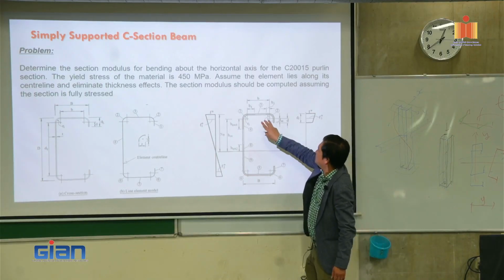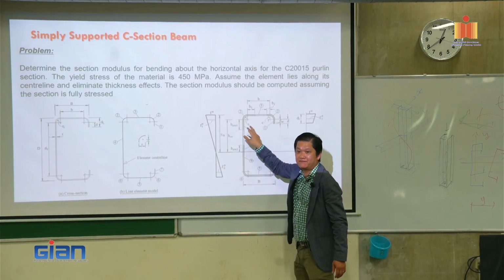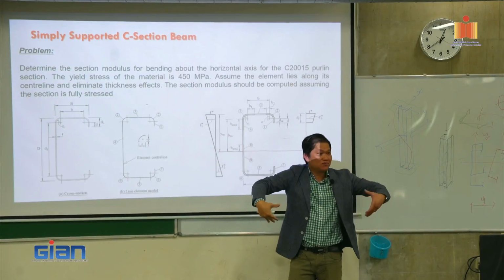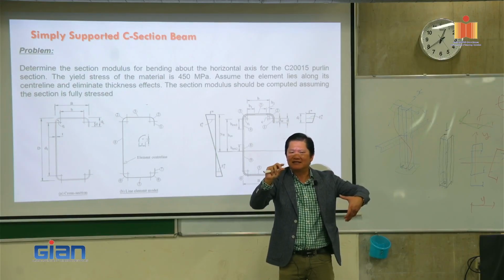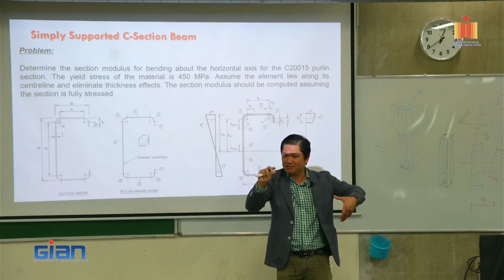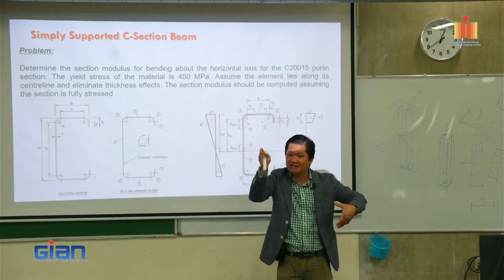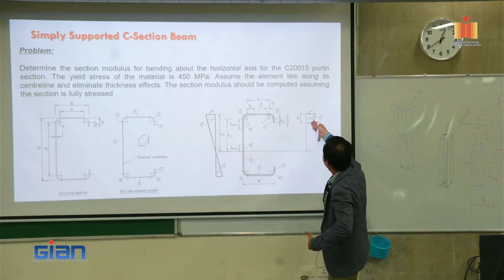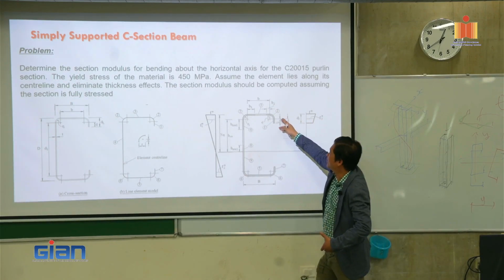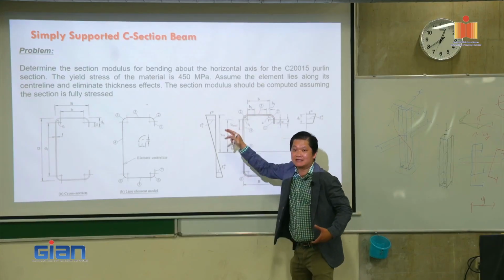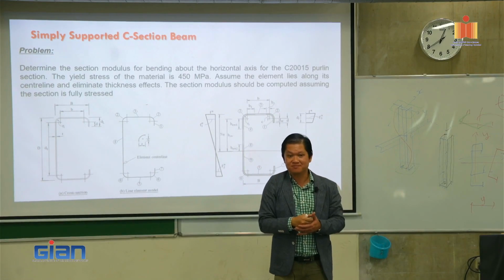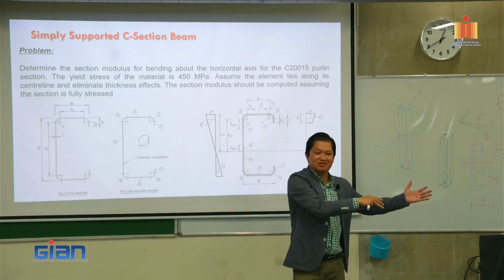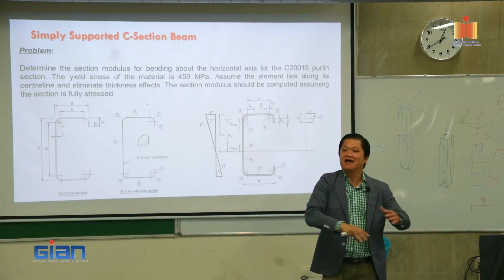For the flange and for the lip, because of bending, the top flange and maybe the lip we can consider as purely compression, because it's very small. We can assume that this stress is uniform, so we can assume that the flange and the lip are in pure compression. All right, and then we come back to our previous calculation, exactly the same.